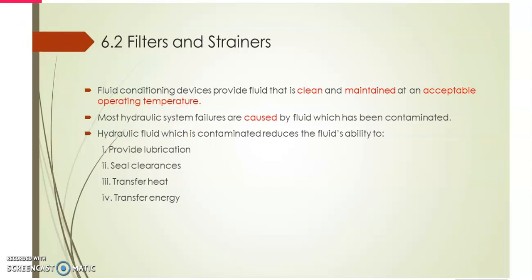Contaminated hydraulic fluid reduces the ability to provide lubrication to the components, reduces the fluid's ability to seal the clearance between the parts, and also reduces the ability of the fluid to transfer heat and energy.